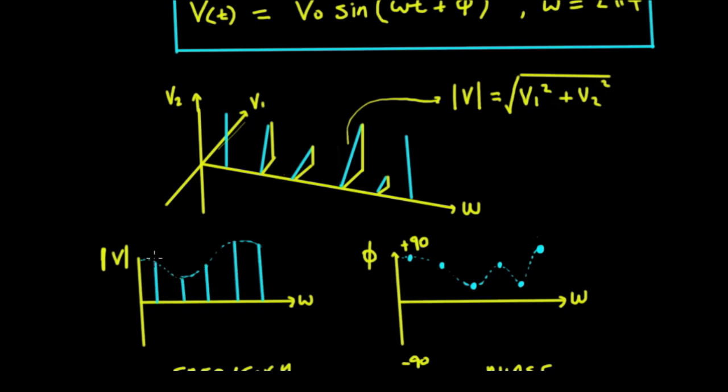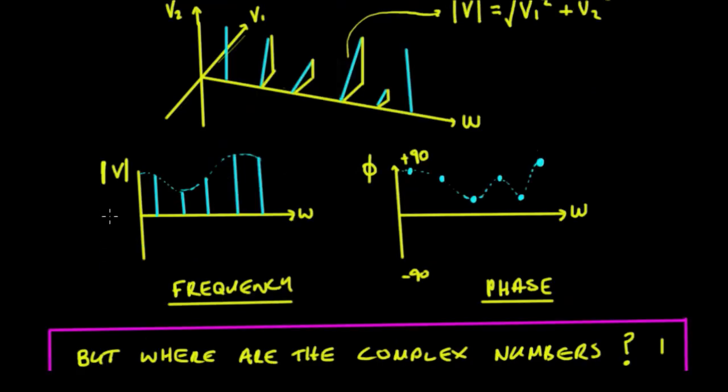Now the height of these phasors is actually going to be the length here, so it's that blue length. Now that blue length is going to be, according to Pythagoras, that squared plus that squared, and you're going to take the root of it in order to get that height. That's why whenever you see this frequency plot, we'll have the frequency along this axis, but it'll be the magnitude of the voltage up this axis. So that magnitude is this length here.